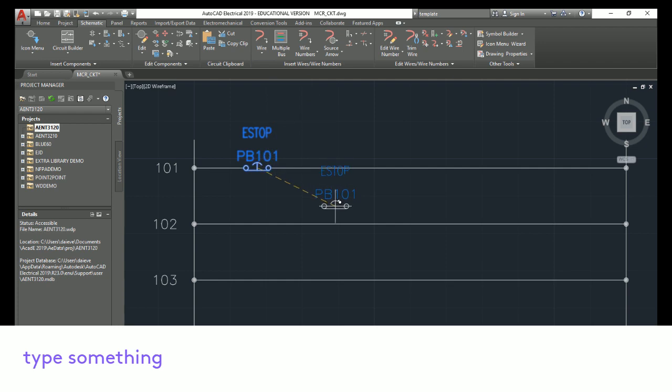If I turn the snap mode on by clicking on F9, what you'll notice is it's snapping to grid elements on here. This can be both annoying and it can be very, very helpful at times. If you're trying to line up to a line, that line is attached to a grid component. And imagine that the distance between each grid, there's a little block, almost like a little microgrid. So I can go from this grid line to this grid line. You can see how it bounces between them, right?